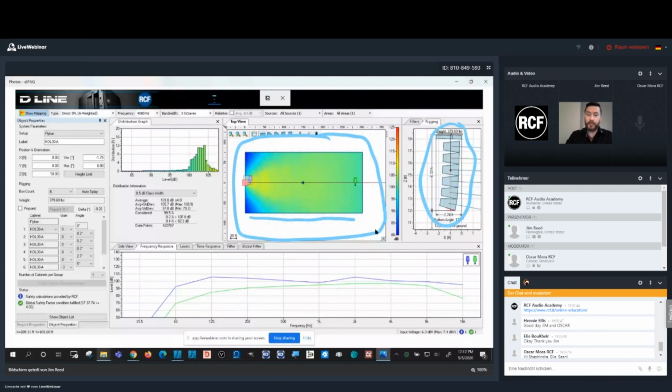And we could also prove that by landing these two receivers to measure our SPL. And if you look at the bottom of the screen, specifically in the vocal range around 4K, they're extremely close. So the intelligibility of the vocal range is going to be consistent from the front row to the back row for a 300-foot area with only 6 HDL30s. But there's an issue.